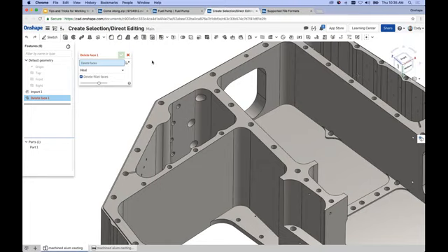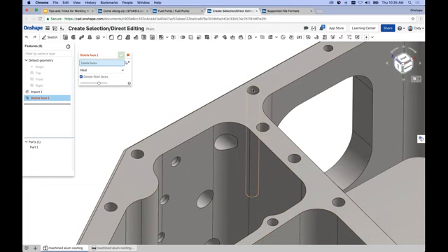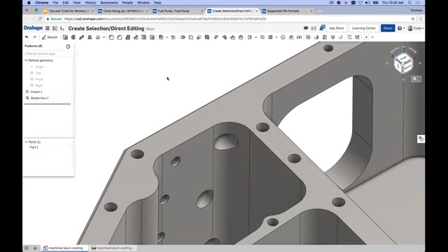All right, so say for instance, I've imported a model and I just need to get rid of a few holes. There are holes in the imported model that I just don't need. Delete face and heal is the tool that I'd recommend, right? Delete face, just select the hole and it will delete the hole, right? It really is that simple.